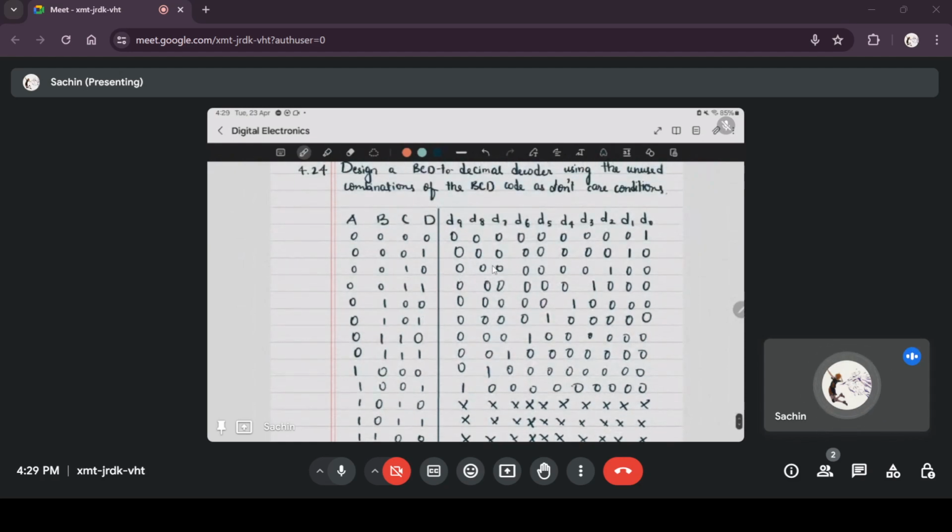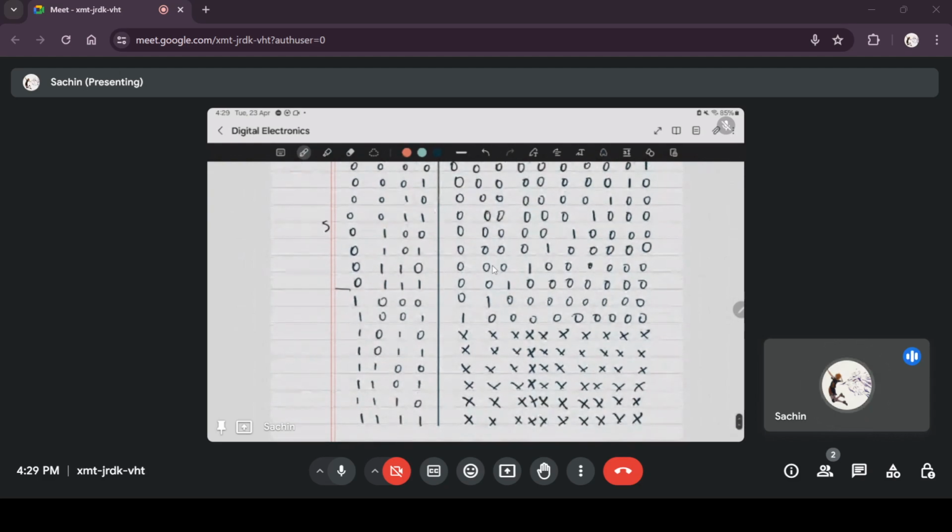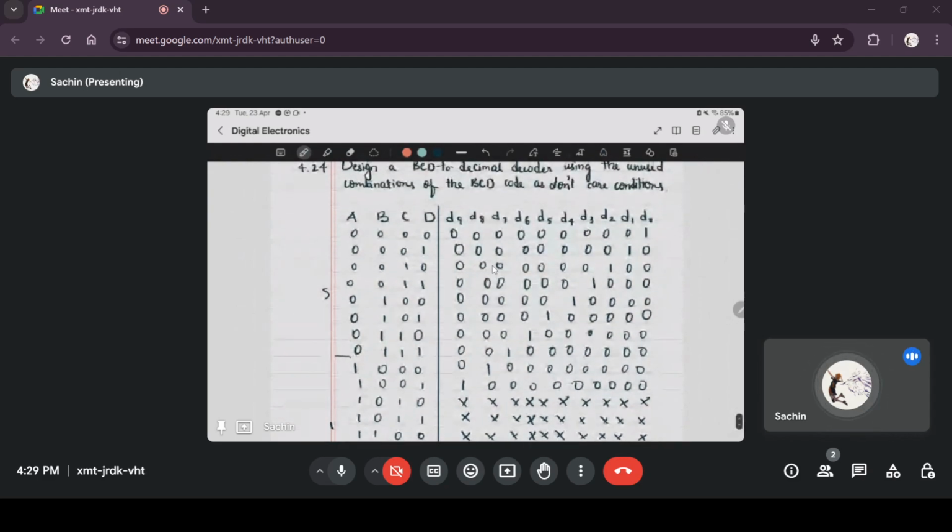And if you look at the truth table, in the first half of the input combinations the MSB will be 0, and in the second half the MSB will be 1. Next, within these half blocks, now that you already split this map based on the MSB, you forget the MSB and look at the remaining variables.